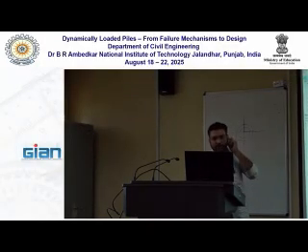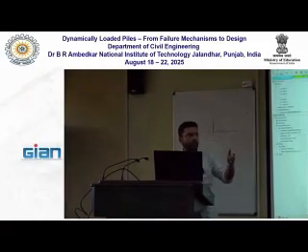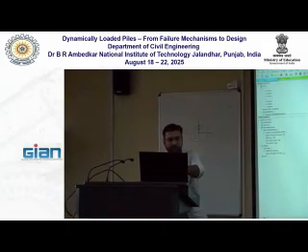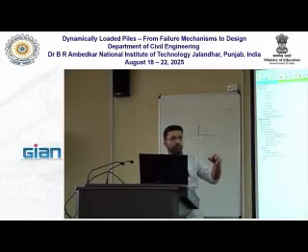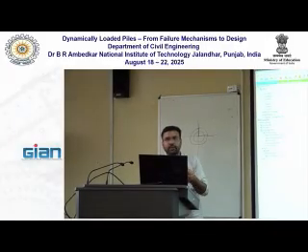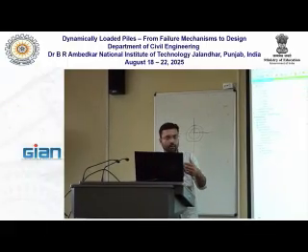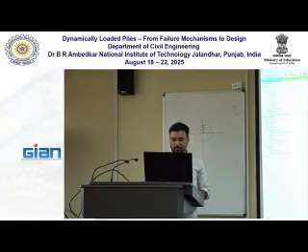There is some value from where you have to start, up to the maximum value. If you skip this axial skin resistance part, keeping it at 0, then after the analysis you will not be able to get the skin friction. So some values you have to assign here. So I am assigning.